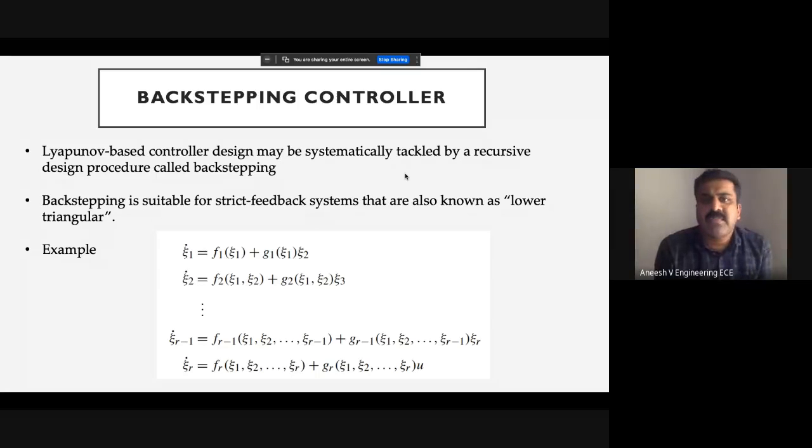So all of you studied about stability. A stabilized system. A simple thing: if we have a transfer function having certain poles and zeros, we can tell that the particular system is stable based on the location of poles and zeros. Simple logic: if in that particular system all the poles are lying on the left side of the S-plane, we can tell that the system is stable.